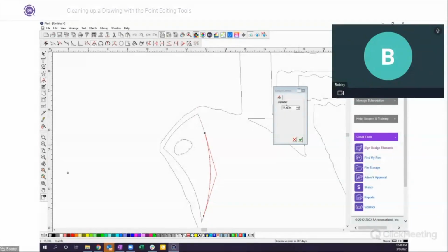And then you can actually define the diameter of the arc. I can make this bigger if I need to, or bring it in, something like that. So you can see the dot that's over here, so I can kind of control that arc. This is probably not the best example of where to use it, but as you see, it's just not controlling it. It doesn't give you quite the control that the 3-point arc does, okay?